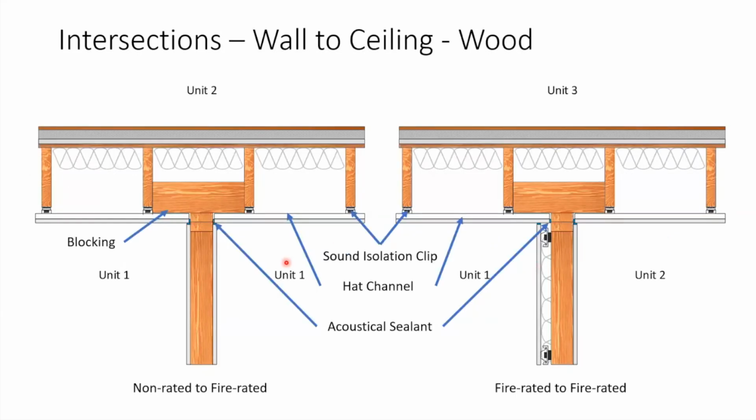Wall to ceiling. Again, in wood frame construction, we can use a double top plate here. We can use the wood 2x4s as fire blocking, and we can break this fire protective membrane, whether we're non-acoustically isolated or acoustically isolated. You're going to need to add some blocking here because you don't want to tie this wall into whatever your acoustic isolation is. Acoustic isolation is meant to allow movement. You don't want this wall moving. So you want to kind of keep those things separate.